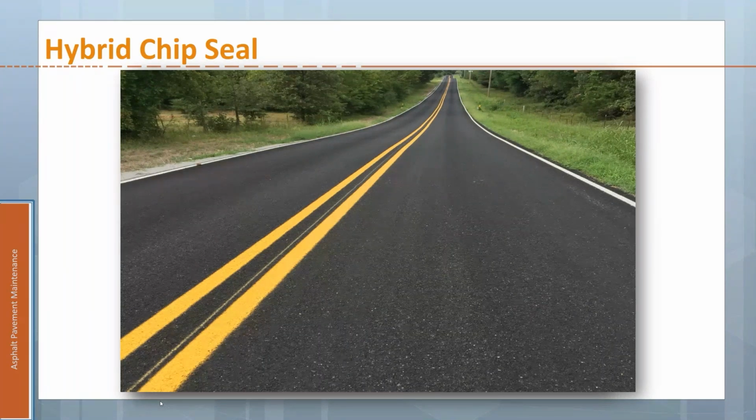So when the project started, these folks had had an asphalt roadway, and then that first layer of chip seal went down, and most of them were pretty upset that we were turning their road back to gravel, which is a common complaint. But when they finished the project, those folks were very pleased with how the road looked, how it drove. It was smooth enough to suit pretty much everyone except bicycles. Bicycles weren't real thrilled with it because it wasn't quite as smooth as an asphalt mix.